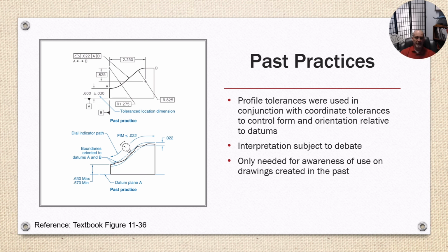So you'll need to know that standard if it says a date on it older than 2018 on the standards. And avoid continuing that practice when revising an old drawing. So the idea is that you uprev it to the current standards.